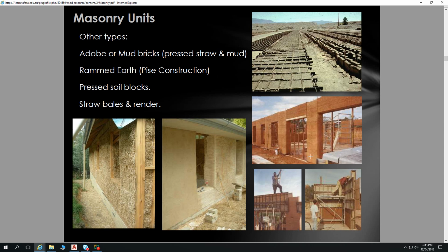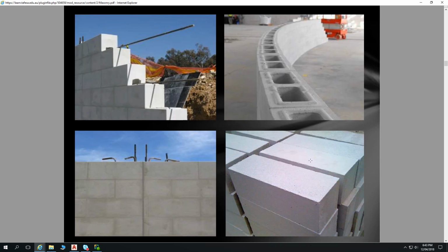What I think is still a very good application of rammed earth is as a central spinal wall in a building. So you get all that thermal mass inside the building. It's great in load bearing. It's really poor in insulation, so you don't want it externally, but it's great for thermal mass and getting inside the building, and it's a beautiful feature as well. It's lovely. Well, I think so. Each their own. A bit subjective.